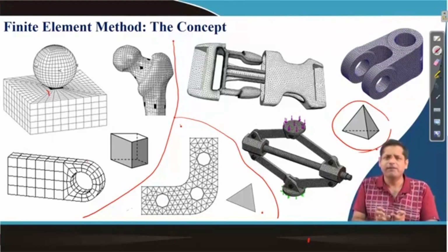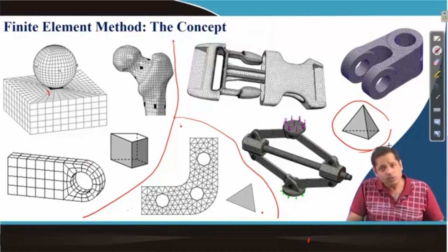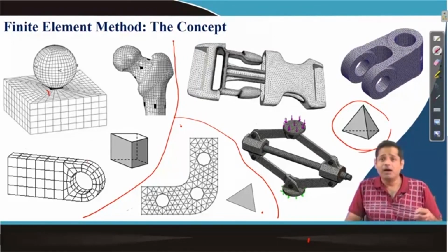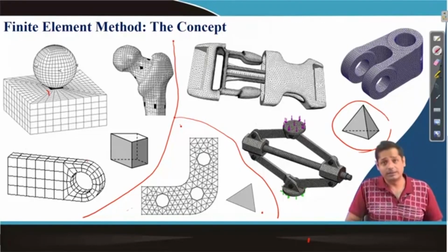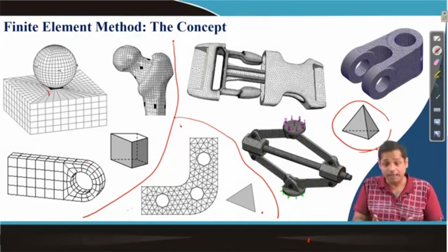But for some simplified systems, without using the equations directly, we can form these element level equations, and that is called the direct approach. And the direct approach you have already used in your structural analysis course, for instance, the direct stiffness method. You have done essentially that.